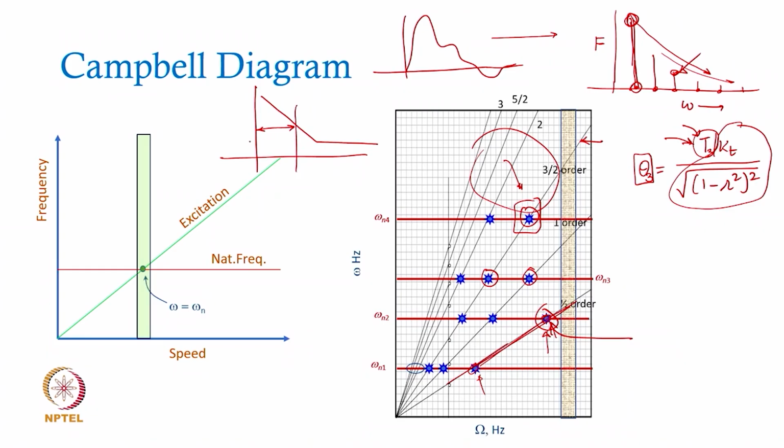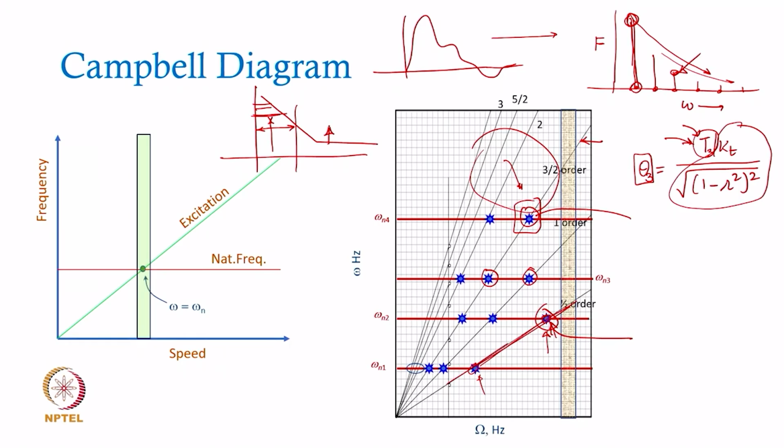If we make small mistakes in assessing the vibration amplitude, this position is going to shift higher and higher, and my life is going to be shorter and shorter. Now, even if the amplitudes here are small and the corresponding stresses in the component will be of smaller magnitude, but if it is more than this, the frequency associated is also important.